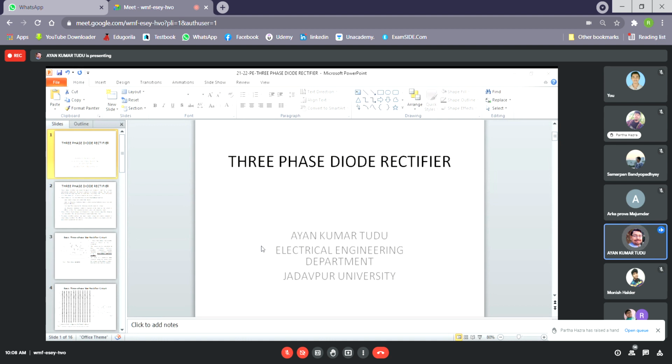Now these three-phase AC to DC converters are used for power output rating of higher than 15 kilowatt. So what are the advantages? These polyphase rectifiers produce less ripple voltage, it means less ripple output voltage and current compared to single phase rectifiers. The efficiency of these polyphase rectifiers is also high, while the associated equipment required is pretty low.